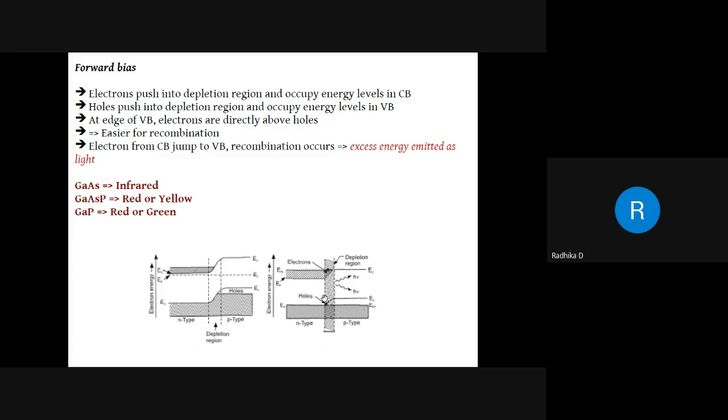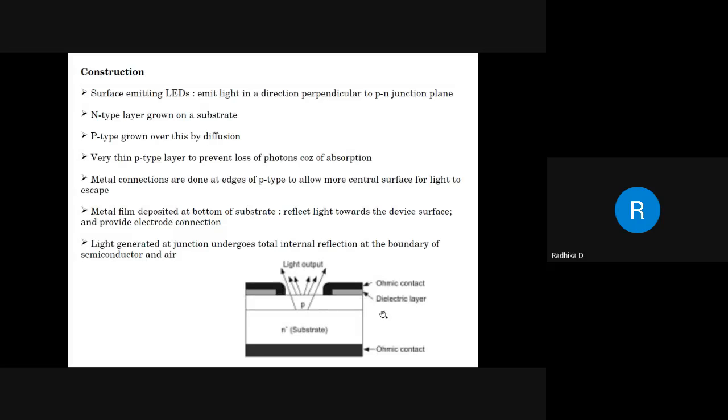Okay. So the electrons reach the conduction band and the holes reach the valence band. But the only thing is, this entire process happens in the depletion region. Electrons jump towards the holes and recombine, but when they jump, they have to release energy, and that energy is released in the form of photons or light. Now, coming to the other question on why it doesn't happen in a regular diode, here comes a reason.